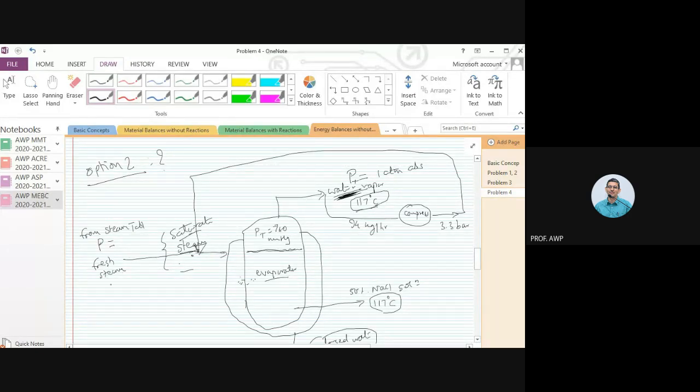And what I wanted was 111 kg per hour. So fresh steam required would only be approximately 111 minus 94, maybe 17-18 kilograms. Do you agree with that? Yes or no? Yes, sir, but we'll have to even heat this, right?